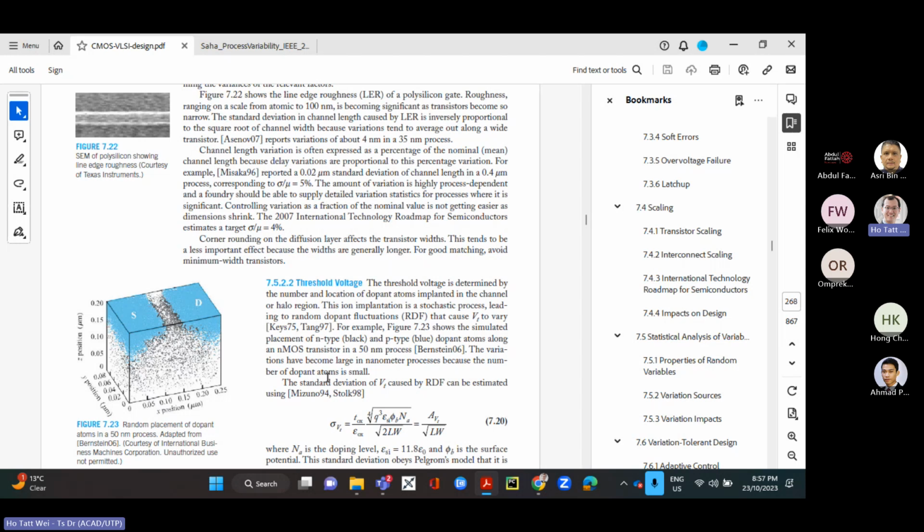Normal distribution is more natural, because of the law of large numbers. So what you normally hope for is that your threshold voltage, the design parameter, will be the mean value. If you want your threshold voltage to be, let's say, 0.2 volts, you design your transistor to be 0.2 volts. So your hope is the mean will be 0.2 volts. But there will be a standard deviation, a variance of threshold voltage that you will be able to fabricate, right?